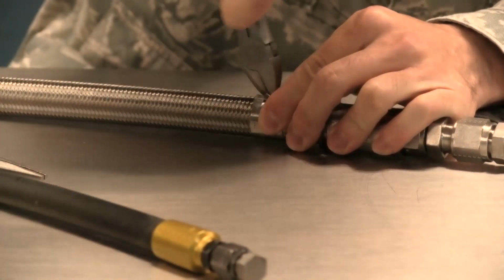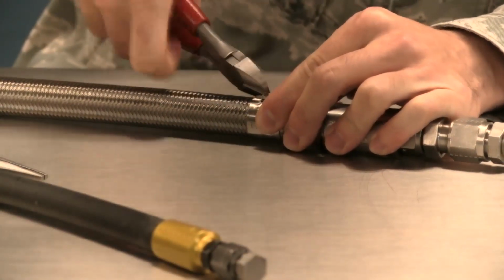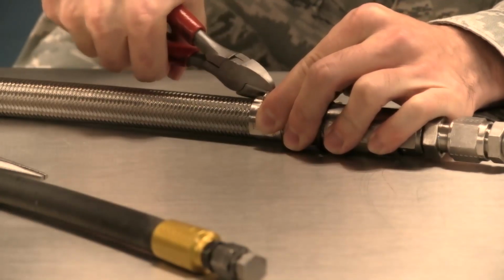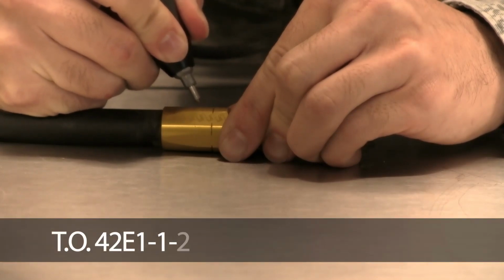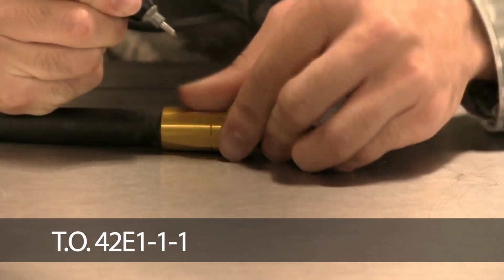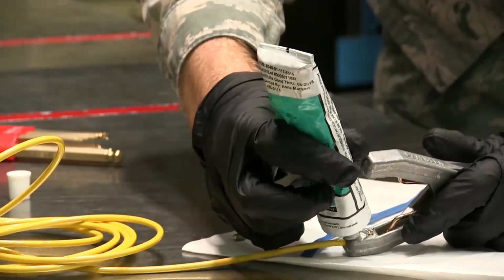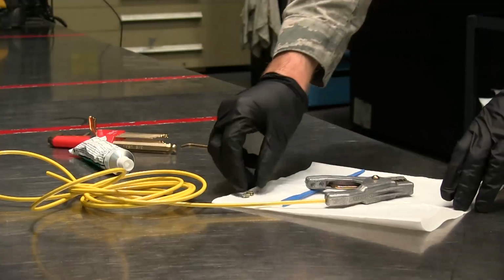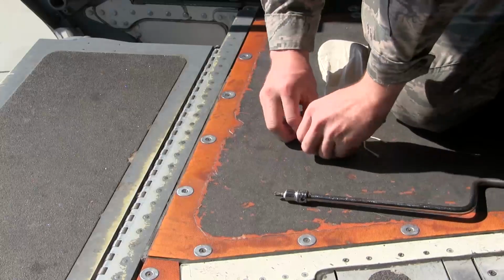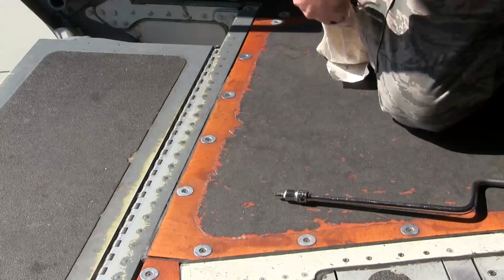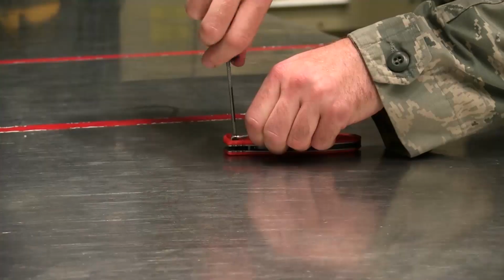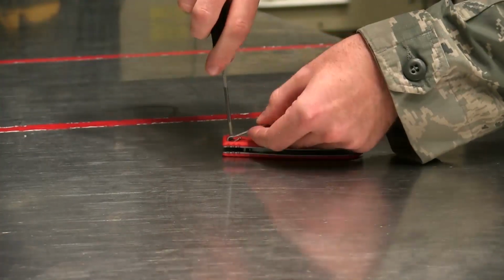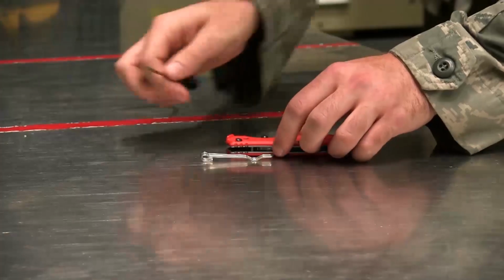Remove all metal identification bands on tubing and cables, except on egress systems, cargo chains, and hydraulic hoses. When removing hydraulic tubing tags, ensure the lines are marked in accordance with Technical Order 42E1-1-1 or any other applicable references. Ground wire screws will be coated with sealant, and unused screws will be removed. Control work order residue used on or around aircraft, uninstalled engines, and AGE. Support personnel must discard removable pocket clips from tools prior to placing in toolkits.